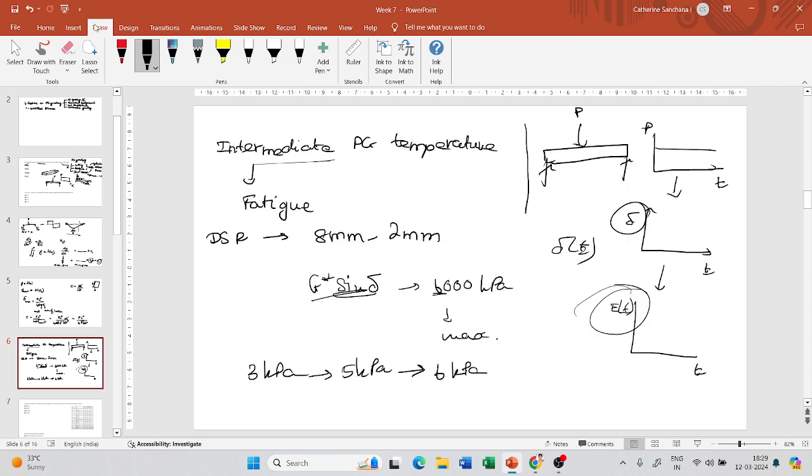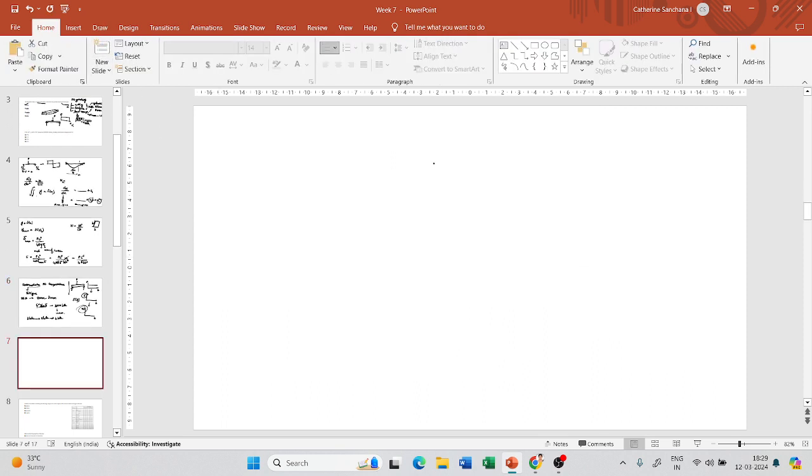So when you give a PG grade for bitumen, you will give something like this. You will not give the grade of bitumen as, say, 21.5 or 20.5 or even 20. You will not give a grade of bitumen like this. This you will call continuous grading, which we will see later. But if you have been asked to give the PG grading, you have to give a particular number, which is not any of these.